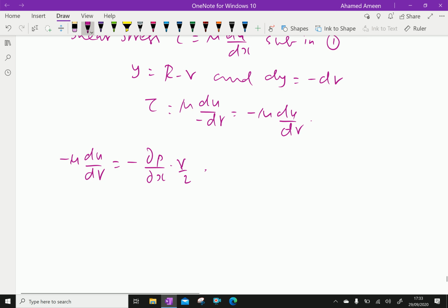Or we have du by dr equals 1 over 2 mu dou p by dou x into r.